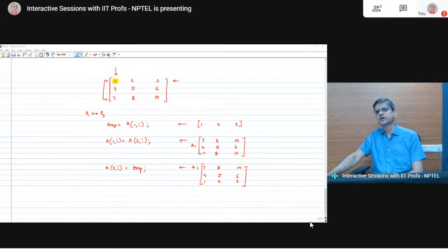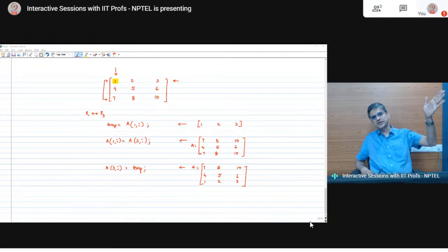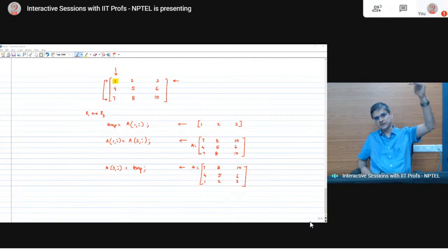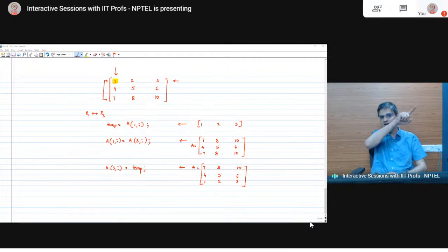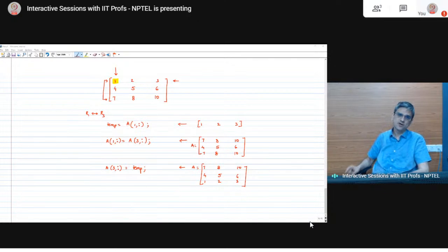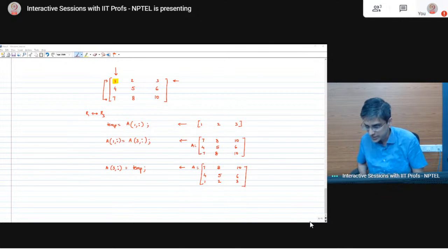But in general, if you want to create a mesh grid, what I would do is have equispaced x, equispaced y as much as possible, and have f of x comma y based on these values. F of x comma y will have n number of rows corresponding to x, m number of columns corresponding to y, and accordingly MATLAB will take those points. Again, you can look at the help for meshgrid and you will be able to know.